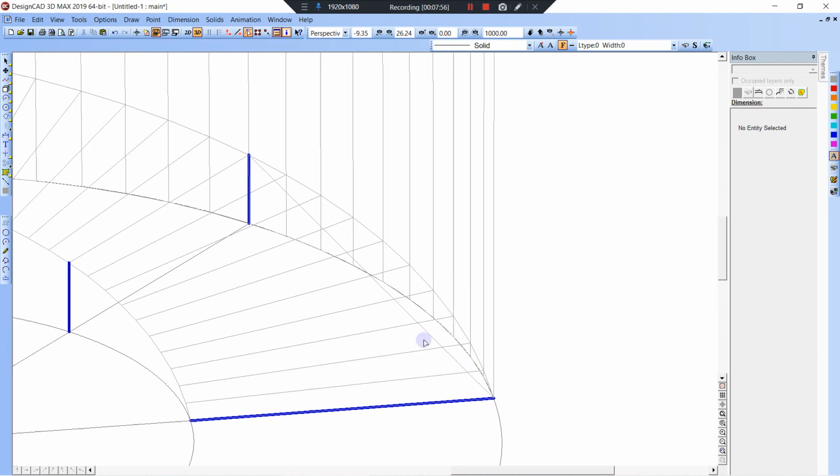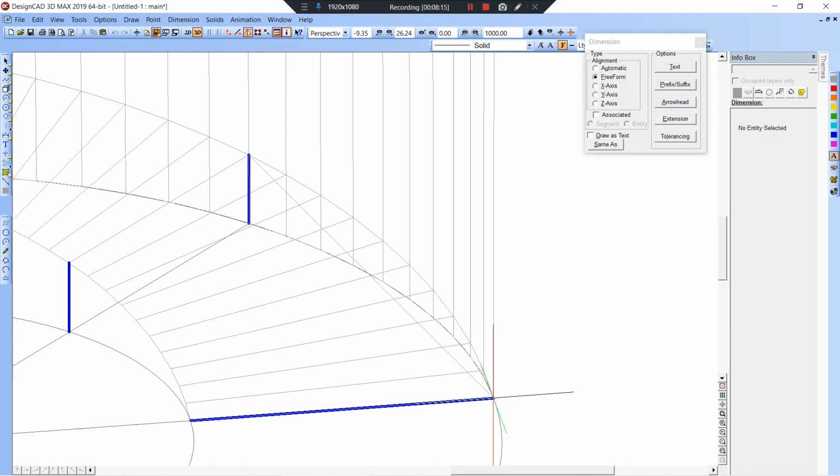So I hope it's not too busy. We're going to take this line, put a nail there on grid at elevation, which we have. You're going to pull it over here, put it on elevation where you have it. And then you're going to find the center of this along the wall. So it looks like it'd be out here. You can't see anything, right?